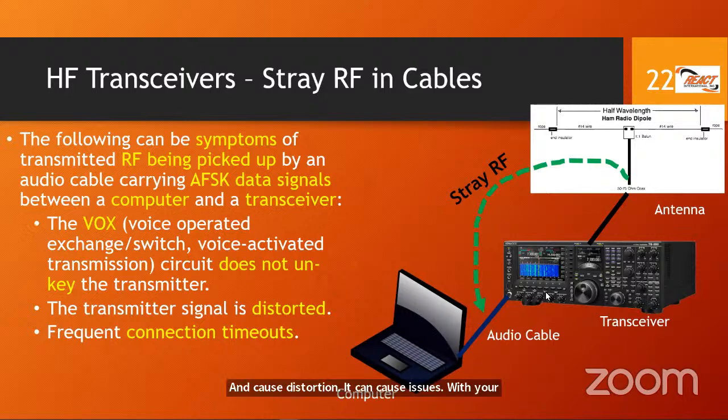It could cause it to key up unnecessarily as well. Feedback, all sorts of issues you can have through what is called stray RF that is leaving either the cable or the antenna and coming and impacting your audio cable connection here. So this is just some extra information for you, and there are things of course we can do, we'll see in a little while, to avoid or mitigate this stray RF.